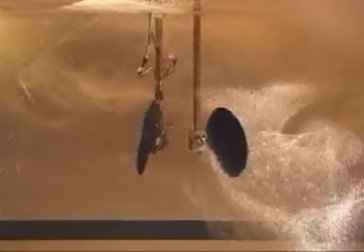Although we usually think of models as being smaller than prototypes, there are cases where it's more appropriate if the model is larger. It's hard to study the aerodynamics of a real fly, for example. It's just too small. Instead, a set of mechanical wings is tested in a tank of mineral oil. This mechanical fly is 100 times larger than a real fly, and its wings flap 1,000 times slower.